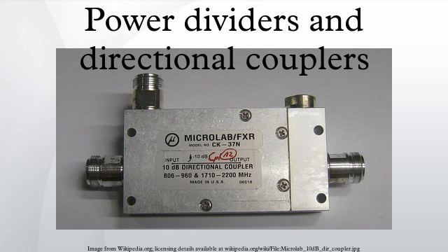Phase difference: the phase properties of a 90-degree hybrid coupler can be used to great advantage in microwave circuits. For example, in a balanced microwave amplifier the two input stages are fed through a hybrid coupler. The FET device normally has a very poor match and reflects much of the incident energy.